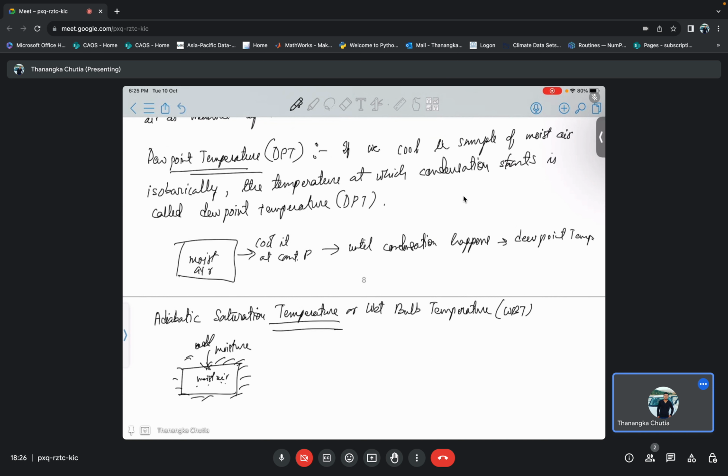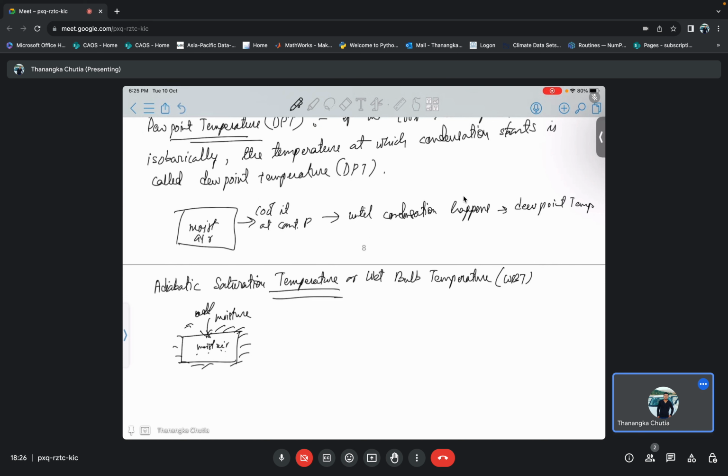Okay, so then how it is achieved is like this, and this is basically an adiabatic container. From here makeup water is passed. From here dry air is coming and moisture is also coming. We know that the dry air mass will remain the same, and this is the exit moisture, m_v prime.